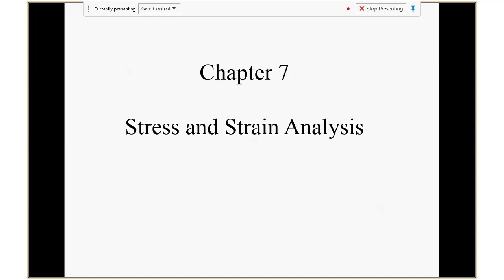So with the stress analysis, we can answer one question. If there is a spot with very high stress, it's going to fail at this spot. But let's say it generates a crack. Which way is the crack going to be? The crack can be 45 degrees, as we talked about before, or maybe 30 degrees or 90 degrees. So you can figure out which direction is the maximum stress direction, and which direction is most likely the failure direction. Remember, we just look at one spot, one point.